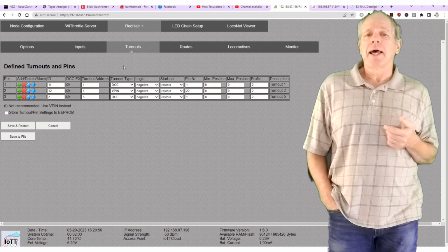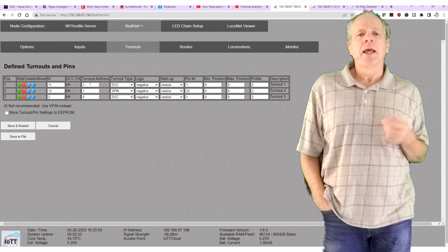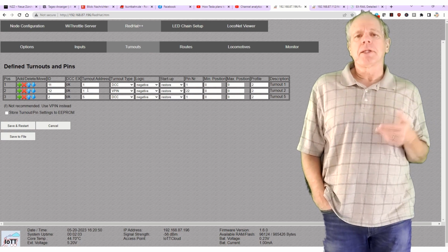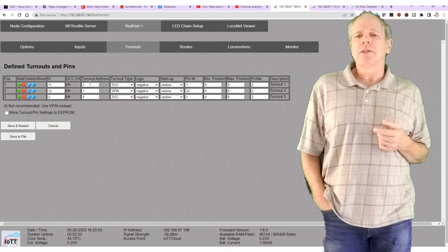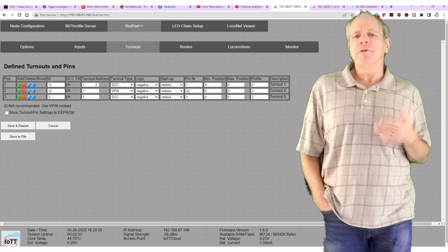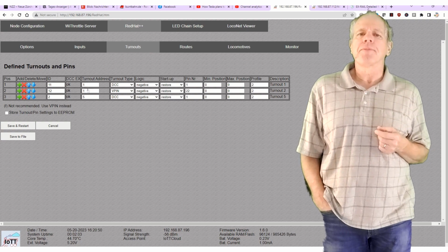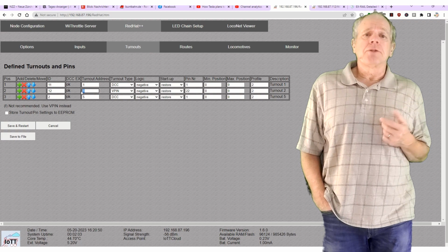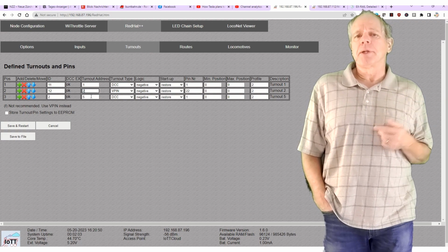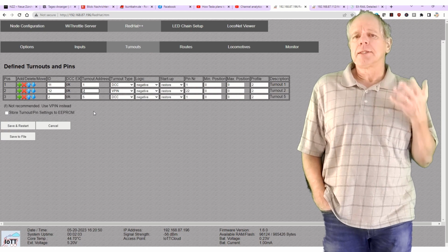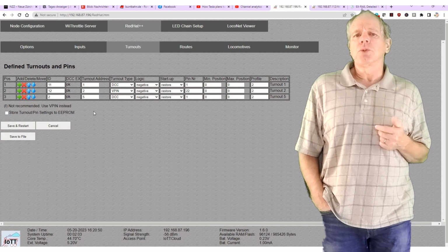Clicking the Turnout tab, I see the list of defined turnouts along with the type. As said in the X-Rail script, the turnouts with IDs 2 and 11 are DCC turnouts, while the turnout with ID 12 is a V-pin turnout operating pin 22 of the Arduino. The LocoNet address for the DCC turnouts is already defined in the X-Rail script, so all I need to do here is setting the LocoNet address for the V-pin turnout, which I set to 2.